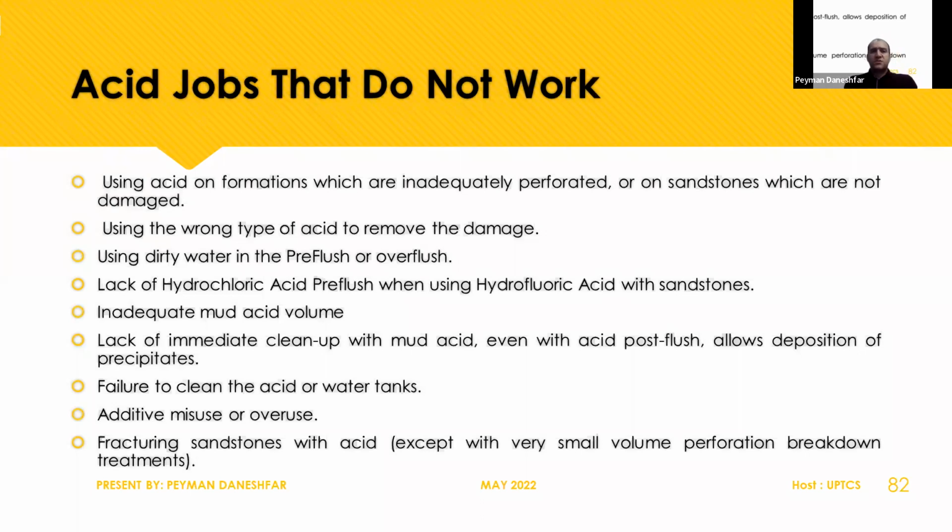And some parameters are important to designing acid jobs. Acid jobs do not work when we don't choose the appropriate rate, appropriate pressure, appropriate volume of the acid or type of the acid, or when there is not good fresh water, or expired additive.